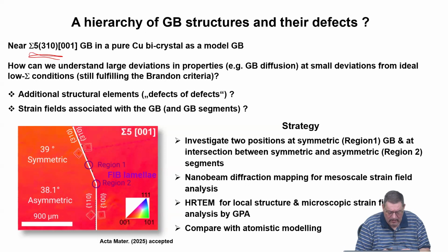So this is an experimental EBSD image of this bicrystal. The white line here signifies the grain boundary between them. And you see that the grain boundary direction changes, which was not intended. But this can be regarded as a feature and not a failure, because this gives you now the opportunity to have, in one material, different types of high-angle grain boundaries present. And related to your twin sigma 3 question, this is sigma 5, but still a highly symmetric grain boundary plane.